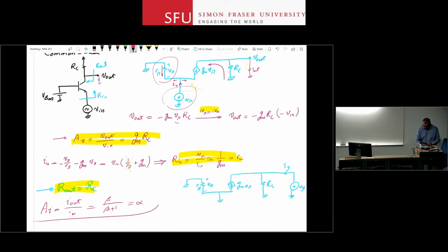And it's not really hard to see why without even analyzing the circuit. You're pushing a current into the emitter, you're taking the current from the collector, you lose a little bit of it to the base, right? How much? Beta over beta plus 1 is the ratio of the collector to emitter current. It is almost 1. We know beta is really large, but it is less than 1. So you don't get a lot of current gain here.